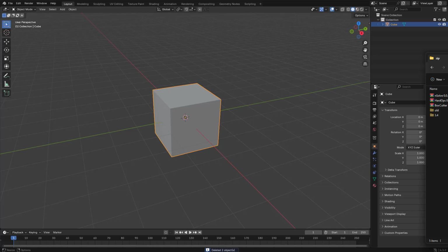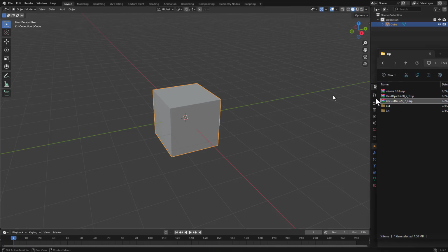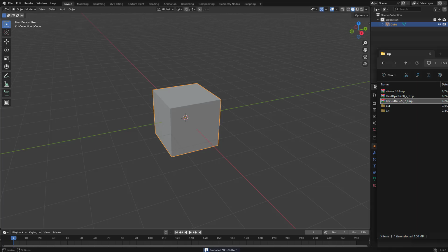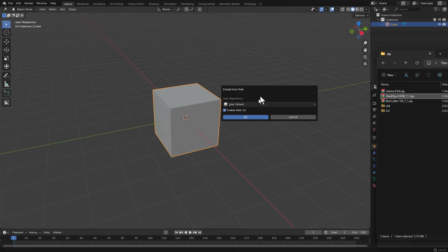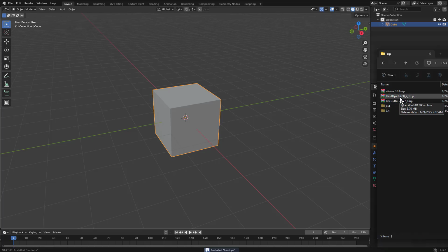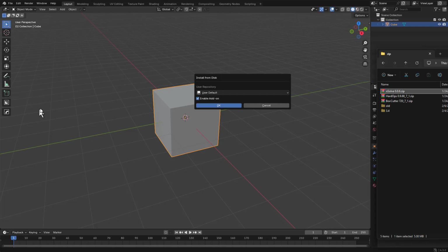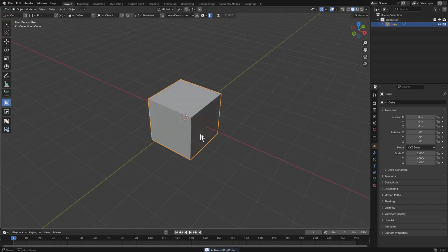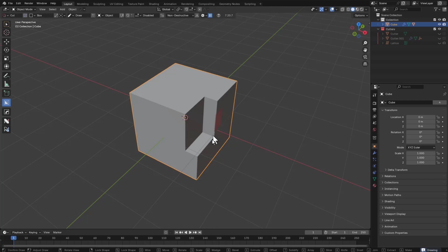So for this, what I'm going to do is just drag and drop these zips onto the window. We'll drag and drop Box Cutter. We will click OK. Now, even though Box Cutter is just updated, I am installing its previous version, even though it doesn't make much of a difference. Whenever it comes to hardops, I am installing 0.9.88_7_1. And then finally, we have Insolve. Notice the icons appearing over on the side. So whenever we bring Insolve, we see that Insolve has also been added, meaning that we now can press Alt-W to jump into Box Cutter, and we can begin working.